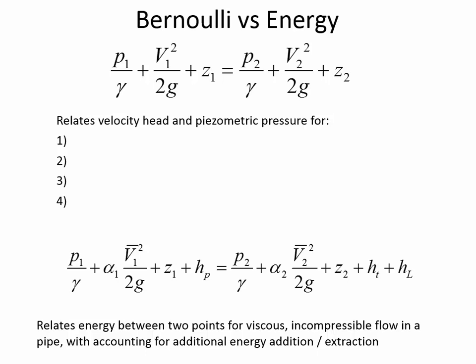If you have laminar flow in a pipe, for example, then alpha equals 2. And for turbulent flow, usually alpha is around 1.03, 1.05. And so just for ease of calculations, it's commonly accepted to let alpha equal 1. So that's what the alpha means. Do you remember what v with a bar over the top signifies? Average velocity, right.